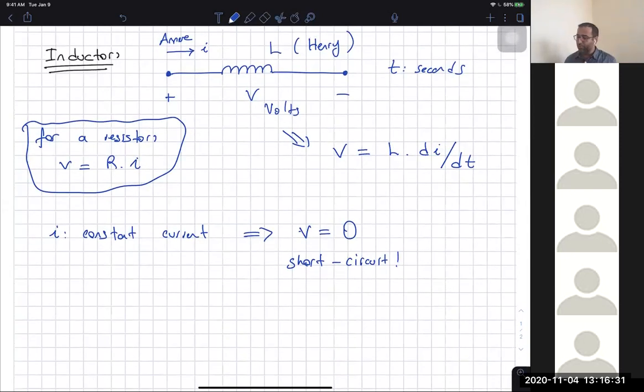So that is something very important, and of course, at the same time, if you again focus on this equation here, the voltage drop will occur based on the magnitude of the change of current. So you will have a component here which will try to resist changes in the current. It's trying to stabilize the changes in the current, because based on that change, it will create a voltage drop here, right? So that is something very important.